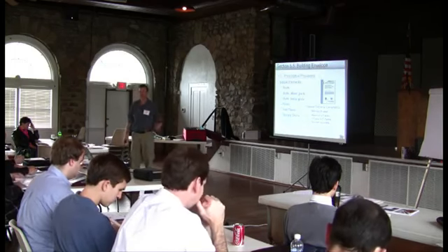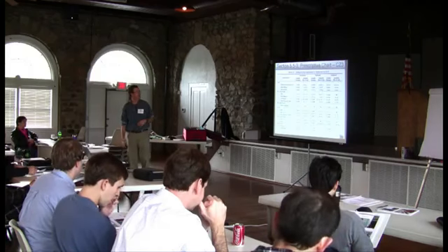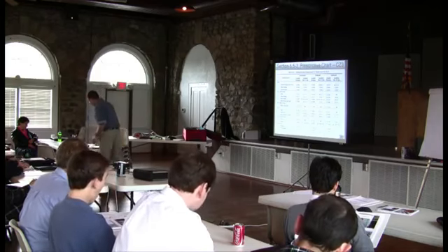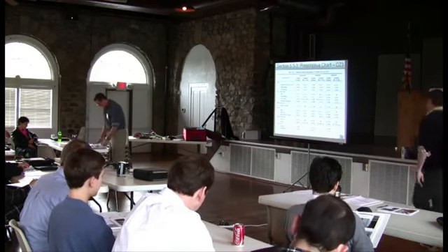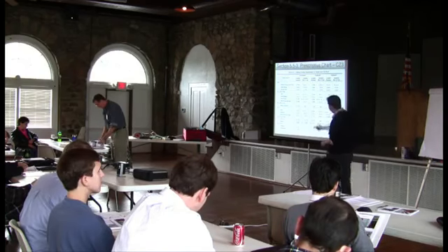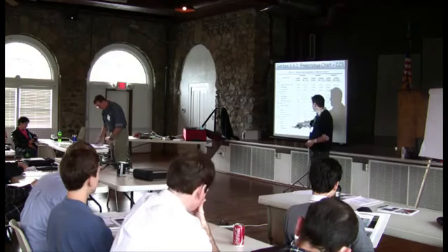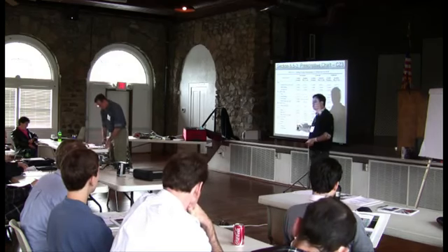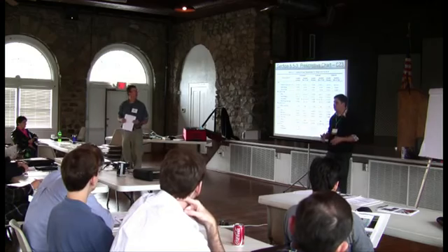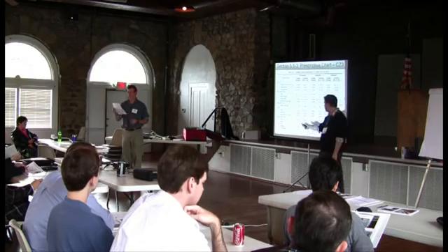So let's take a look at the opaque part of the code, and this is the chart. The envelope splits it up into opaque and fenestration. For all our opaque items, our elements are roofs, walls above grade, walls below grade, floors, slab on grade floors, and then opaque doors. A door, if it has more than 50% glazing, is considered fenestration. But if you have a view light, that would be considered an opaque door.